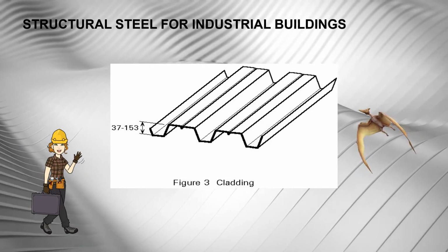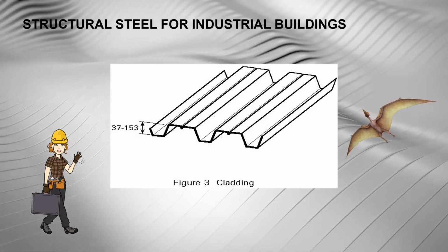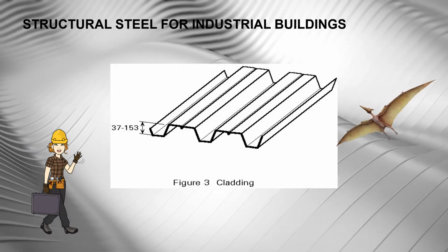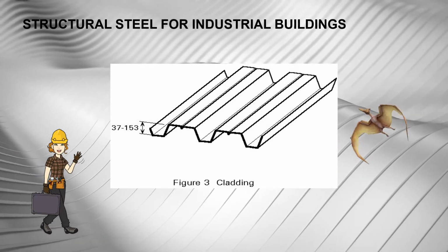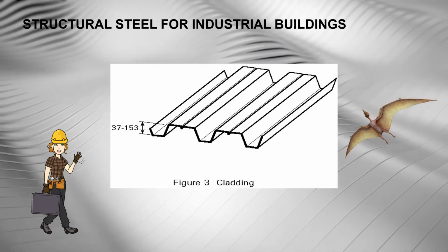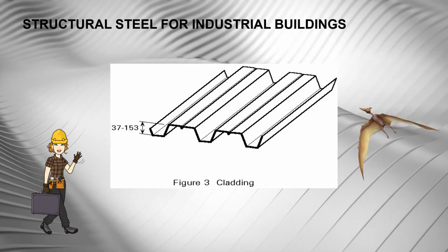In a dry, closed environment, steel does not rust, and protection against corrosion is needed only for the erection period. For other environments, protection systems are available which, depending on cost and suitable maintenance, prevent corrosion adequately.